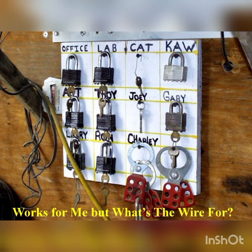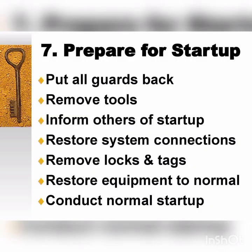When you go for the startup of the equipment, you need to make sure that all the guards are put back, all the tools are removed, areas are properly restored, all the locks are removed, all the energy equipment is properly reconnected and the energy is restored again.